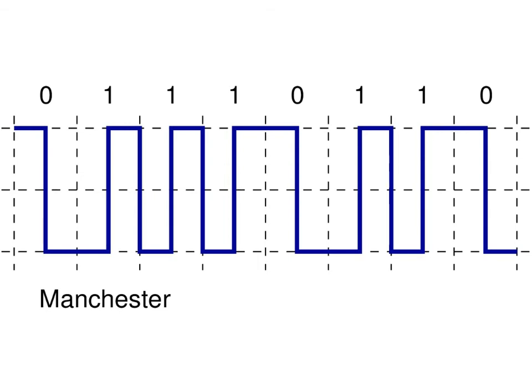What's the data rate? What data rate do we achieve with Manchester encoding? If our signaling rate is 1,000 per second, the data rate is 500 bits per second. We still are the same as the previous ones in that we're still sending 1 bit every 2 milliseconds, so still 500 bits per second, except we need to change the signal at a much faster rate, 1,000 times per second, which is more complex.